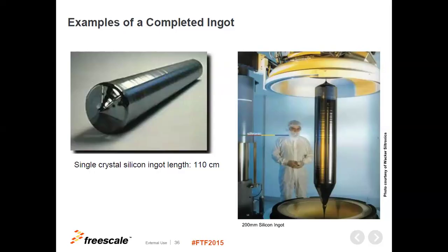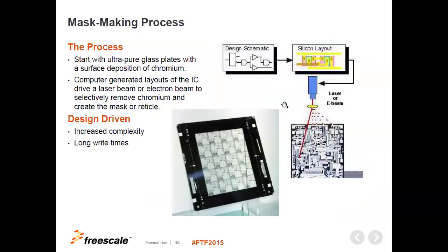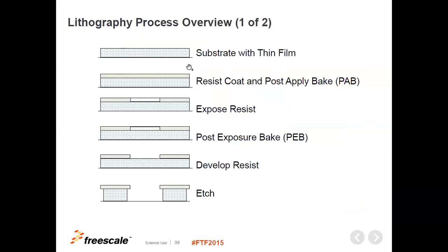Industrially, silicon is melted and put at high temperature in order to create these ingots. The ingots are then cut into wafers, okay? Usually the way they are cut is by laser, okay? Because they need to be very precise, and the thickness of these kinds of wafers is around 640 microns, so 10 to the minus 6, okay? And then we can build up all the things.